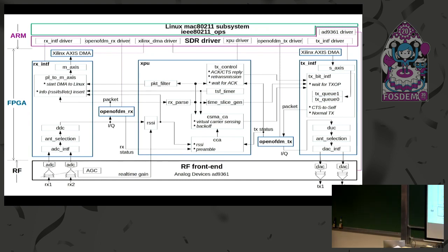In the center is all the CSMA low MAC layer in FPGA. You need lots of functionality. You can check the standards. They define everything very clearly. You need CCA, right? Detect channel is busy or not. Two methods. Based on RSSI, RSSI has to be precise, right? Otherwise, you have wrong answer. Based on preamble, which is from the OFDM receiver status. Okay, you output channel status to the CSMA/CA engine. In this engine, you do the random backoff, right? According to your contention window, etc., all the parameters in the standard.